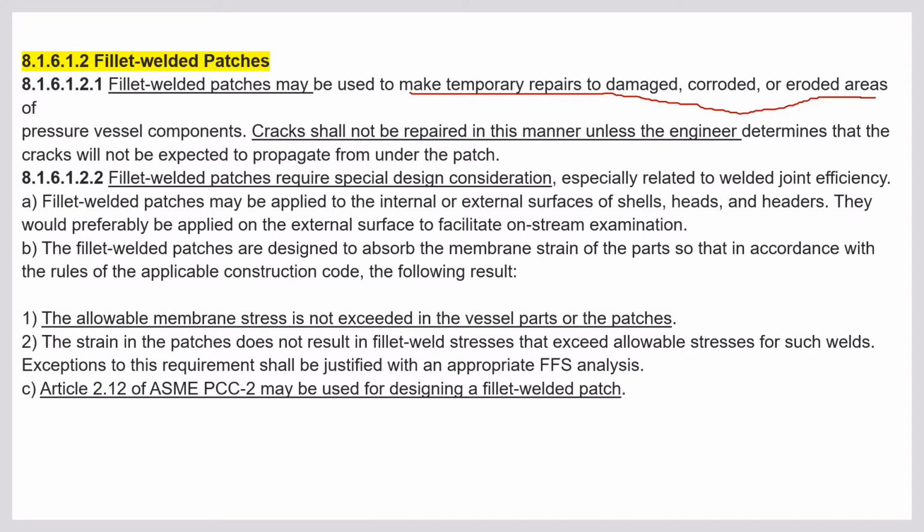Okay, if there is a nozzle and a flow is happening and there is corrosion, due to this flow, this corrosion becomes erosion. Okay, so corroded means naturally corroded, but there is no mechanical flow or pressure on that one. But erosion is corrosion with some flow. Let's say a nozzle is there and a high pressure flow is going through that nozzle, and there is a corrosion developed. So due to this flow, this corrosion will become bigger. So that we call erosion.